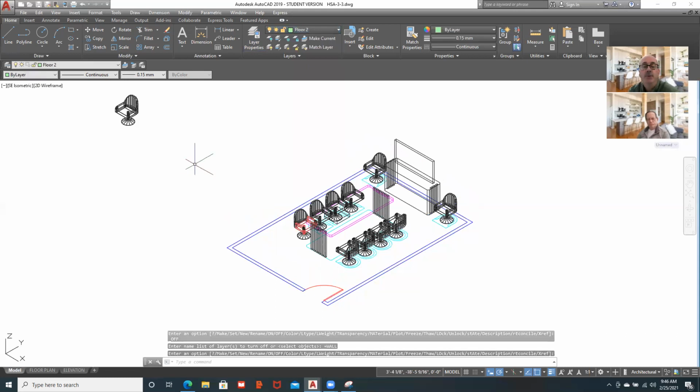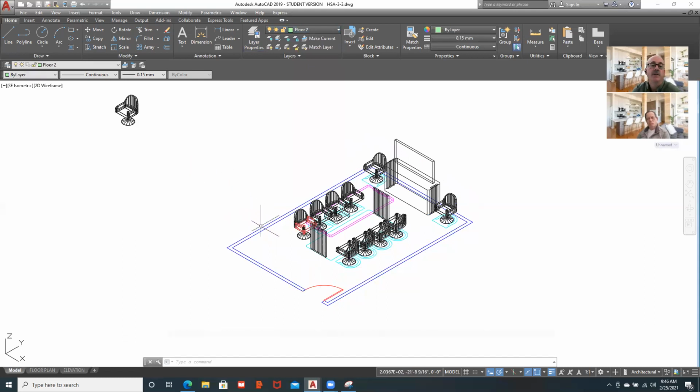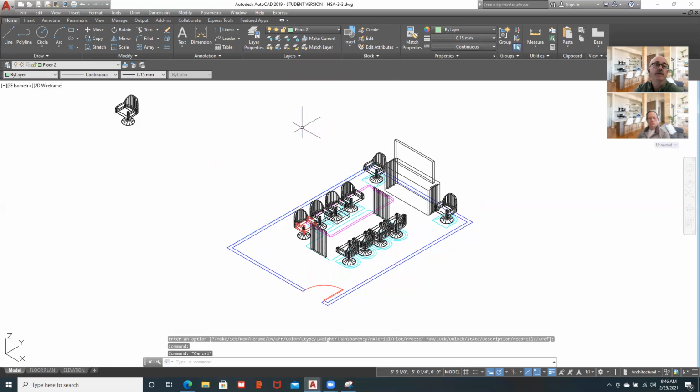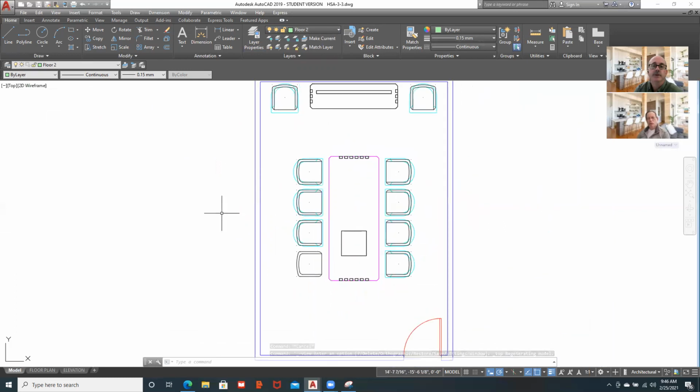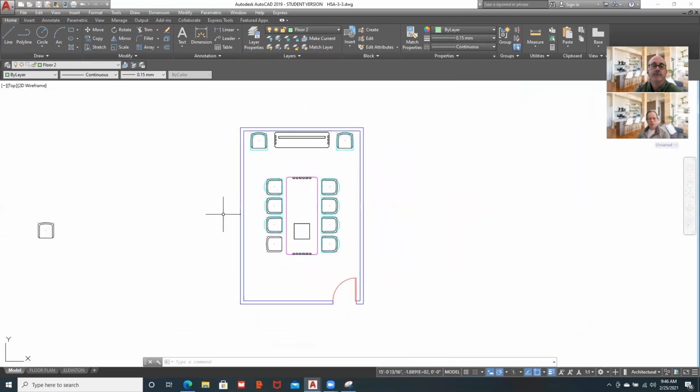Terrific. So what happened was we still have our ghost image of the floor from the 2-dimensional drawing, and it's on layer 0 and it's blue. So that's good for this technique. We'll go back to a top view. We're already on our floor layer. Right. And there are 2 ways of doing it. You can either do it as is and trace over with a line, or you can do it with a rectangle. Go to rectangle, and you want to start off with a top edge.